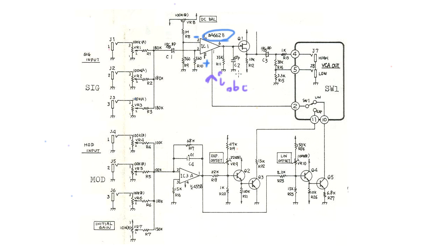So I'm going to guess that maybe they were having some sort of stability issues where they had some sort of parasitic oscillations of some kind somewhere that they were trying to get rid of, or maybe some other high frequency noise source. And that's why they put this capacitor in there to get rid of that. Anyway, it doesn't have a musical effect.